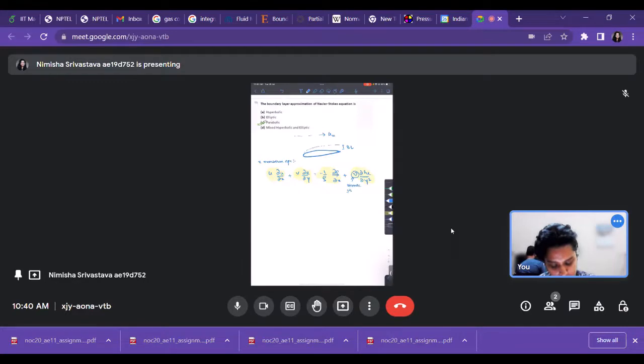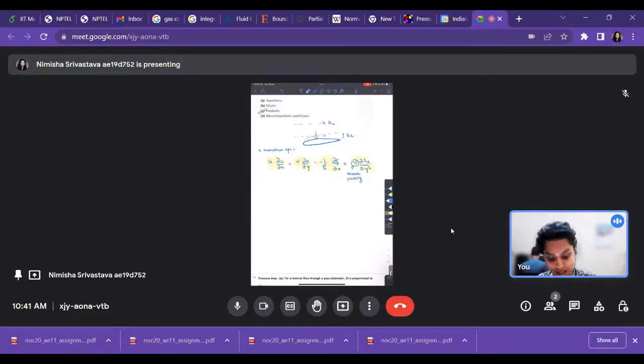Okay. So we see over here that we have the advection terms, we have the pressure term, and we have only the viscous term in the y direction, because the viscous term in the x direction is very small. Again, because the gradients in the x direction in this sort of situation are going to be very small as compared to the gradients in the y direction, because that is a very drastic drop. So compared to the viscous terms in the y direction, the viscous terms in the x direction are effectively negligible. That is the idea behind this equation.